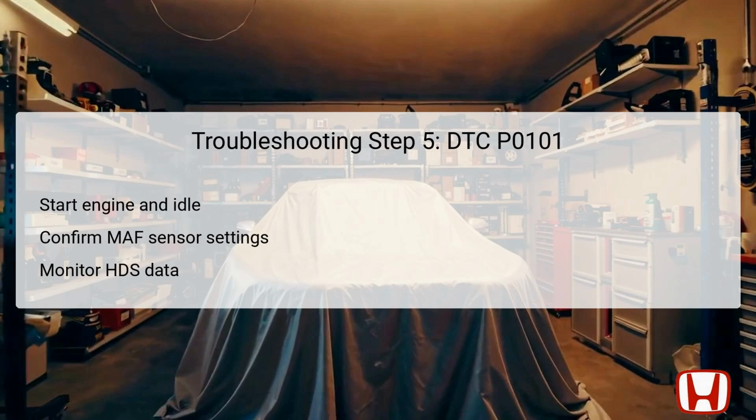If the readings are abnormal, it lends further evidence to a potential fault within the MAF sensor or the integrated IAT sensor. This examination is a vital checkpoint, confirming whether the components are working properly while the engine is operational, thereby impacting overall vehicle functionality significantly.